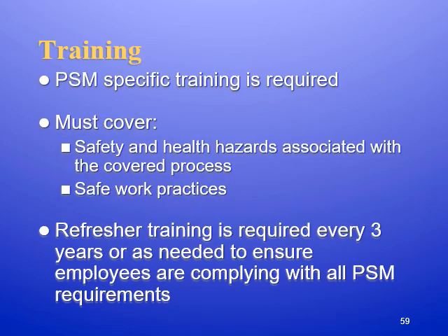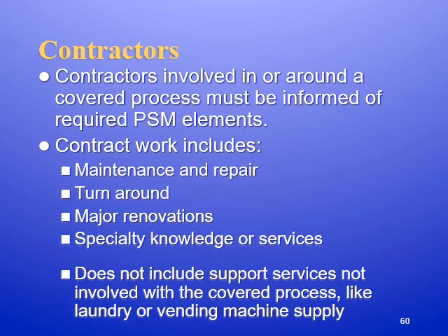Training is also required. It must cover safety and health hazards associated with the covered process. The HAZCOM standard under OSHA still applies, but may overlap with this standard. It must cover also safe work practices. And refresher training is required every 3 years or as needed to ensure employees are complying with all PSM requirements.